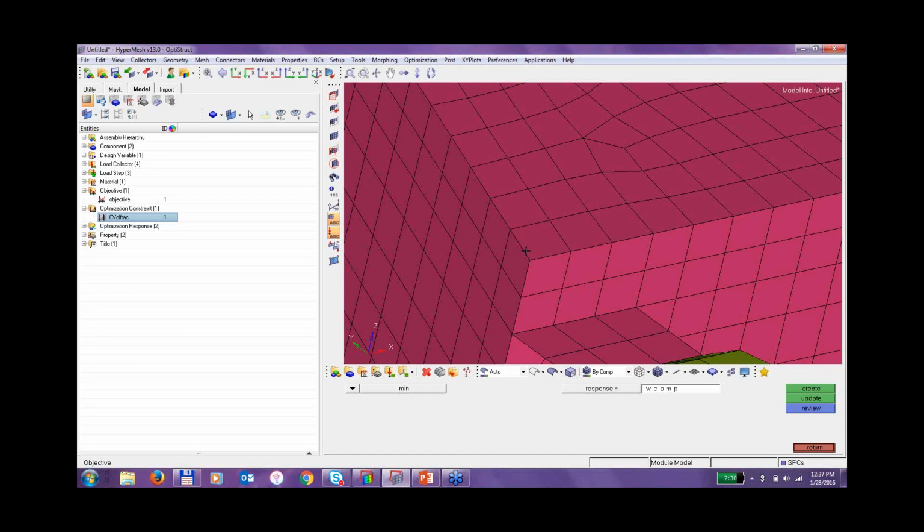If I multiply the Young's modulus by 0, or at least a number incredibly close to 0, since 0 technically doesn't work out mathematically, I'm essentially saying that element has no structural integrity whatsoever and is not contributing anything to the analysis.